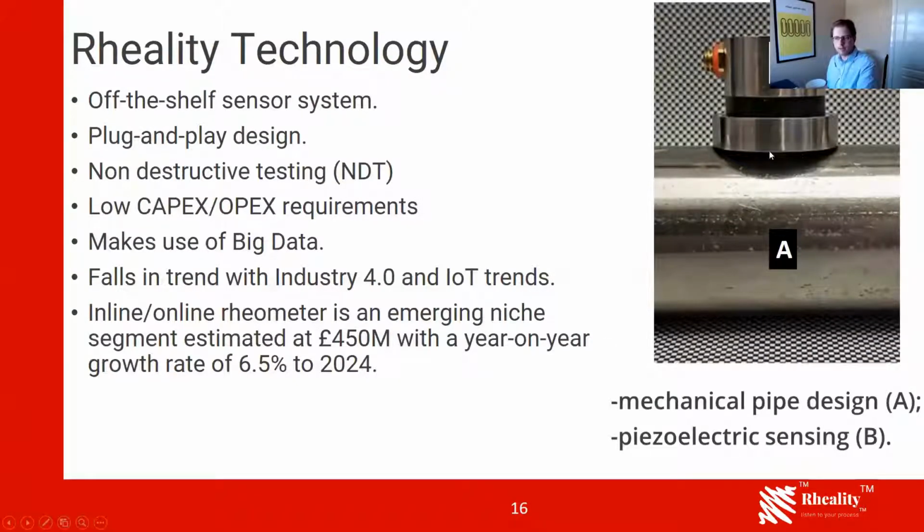I said this would be the part where the sensor is sitting on it, and basically throughout this one, the depth of the radius would be the best resolution. You can have it shorter or longer. This is just a standard execution. Basically, the radius would give you 100% resolution. But for example, for the Scandinavian customer, they want a very short and thick pin bit. But yeah, there is a protrusion into there, a little pin where the fluid would pass by, which is necessary purely to convey the signals or the energy releases between the fluid and the sensor.